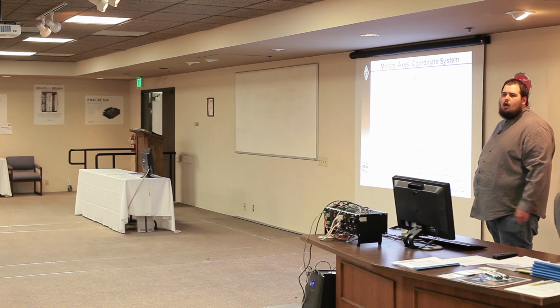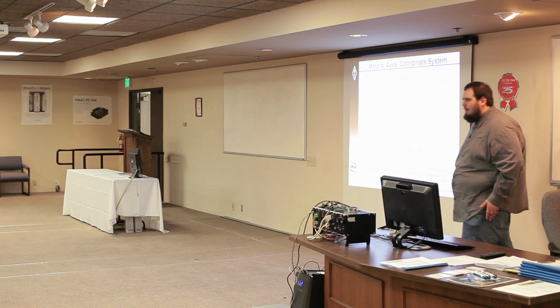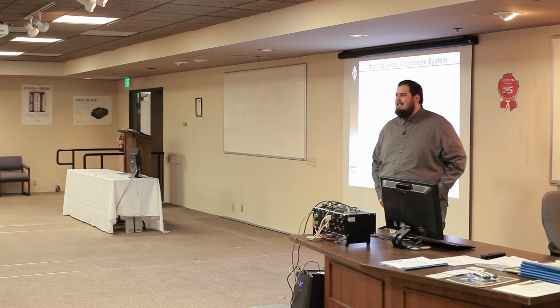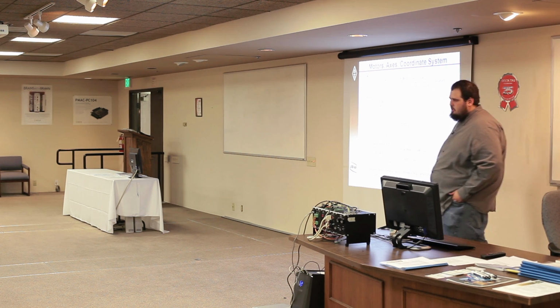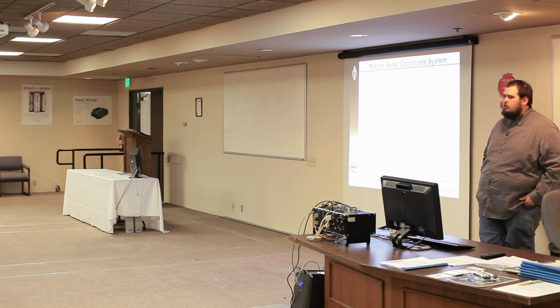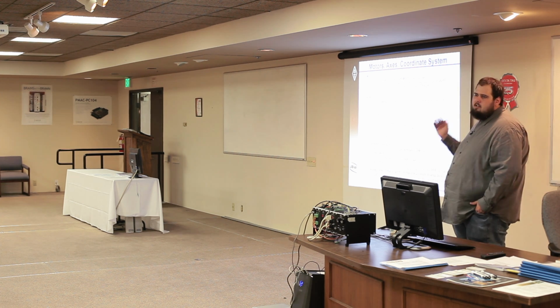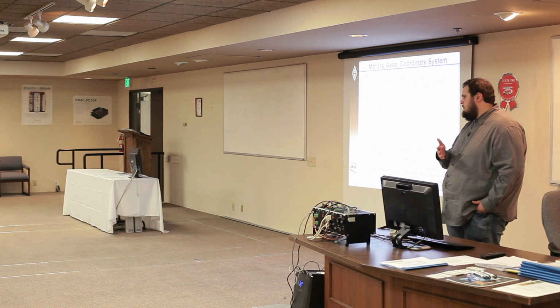So if you ever issue just a motion of a motor, that motor by default is being assigned in coordinate system 0. As a couple of students found out with the percent command, which affects the time base, it is coordinate system specific. So if you are just issuing a time-based command in the terminal window and you haven't done anything, that time-based command is being issued in coordinate system 0.